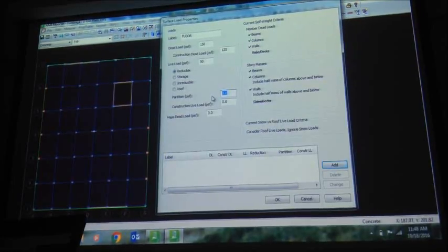Partition. Those are all partition loads, these walls. Those are all partition walls, so usually what we do is partition walls are not shown. It's a partition, that means it's temporary. You can break it and move it somewhere else. So the way we do it is that we assume that it gives a uniform load on my floor. So usually partition loads are 10 psf.